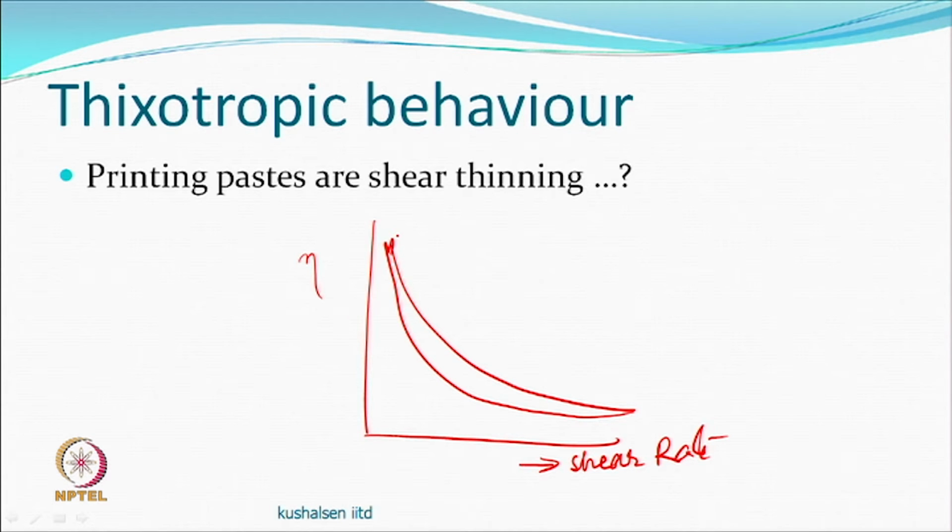Similar is the case of the melt spinning or wet spinning. When polymer solution is pushed through the spinneret, the viscosity around the spinneret and through the hole becomes very low and just passes through that. And after that, of course, there are other processes with which it solidifies. Our aim is different. So, this thixotropic behavior of our printing paste is an important characteristic of the paste. Any polymer which does not give us this is also not so good.